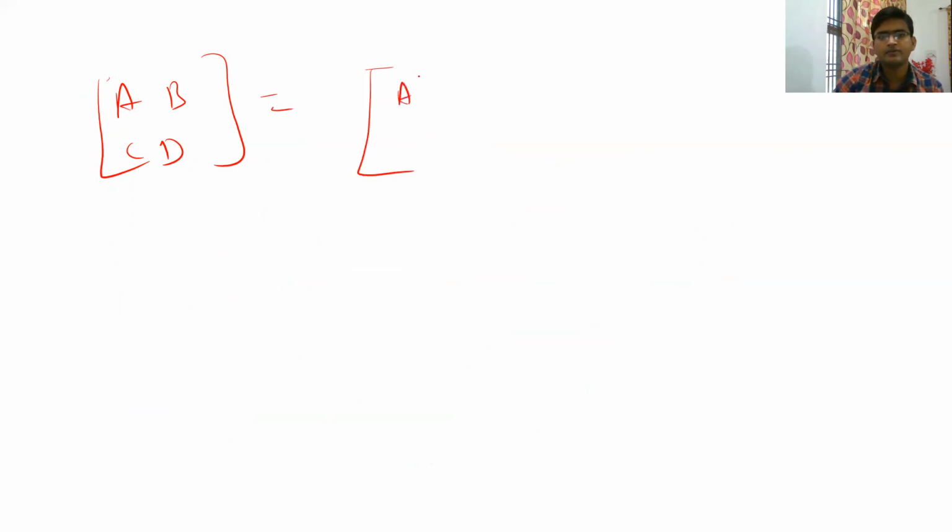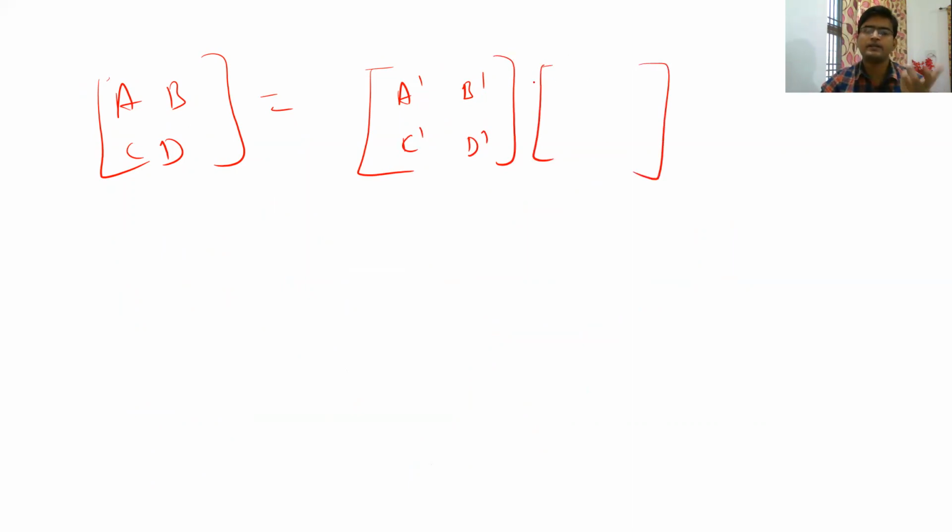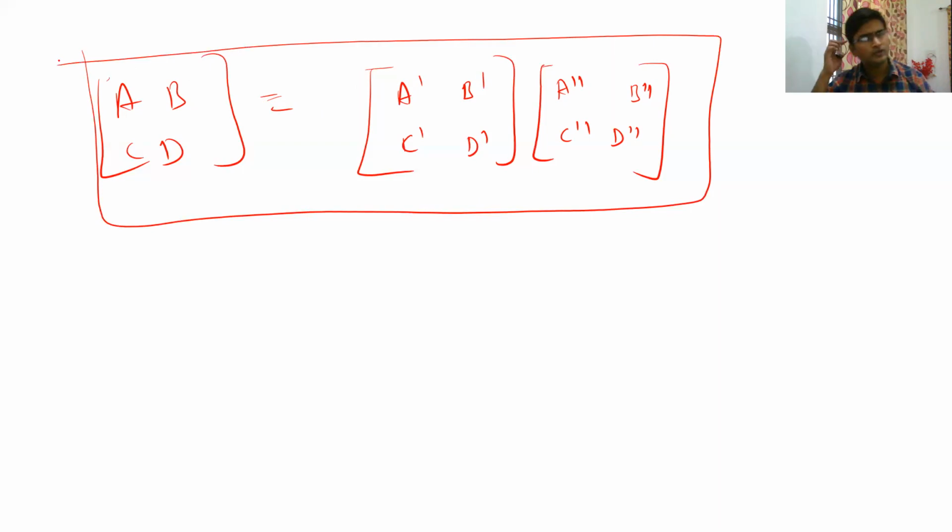You will get that the final ABCD parameter for a cascaded network is nothing but the matrix multiplication of these two individual ABCD parameters. So you simply calculate the matrix multiplication of the two individual ABCD parameters, and you will get the overall ABCD parameter for the combined network. So this is how you use the ABCD parameter for a cascaded network.